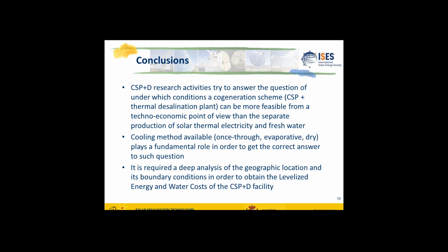And we have all the advantages that we have mentioned in the previous configuration. And obviously, the fourth configuration is the one that I don't like to say is cogeneration. This is typically the idea that I have my power plant, that I can put in whatever location I desire, the most appropriate, and my idea is to produce all the electricity that I can, and at the end I use part of this electricity to drive a reverse osmosis plant. In this case, there are no penalties in the efficiency of the power cycle because we are still working at the same conditions as when we have the standalone power plant.